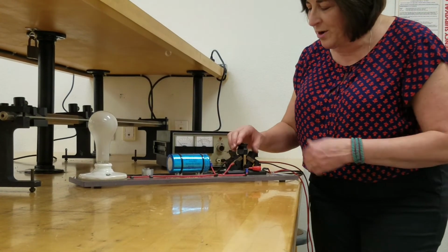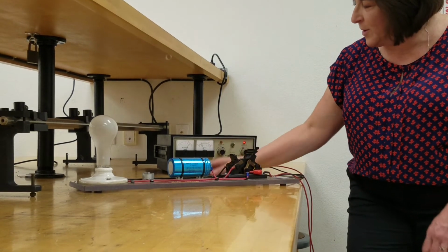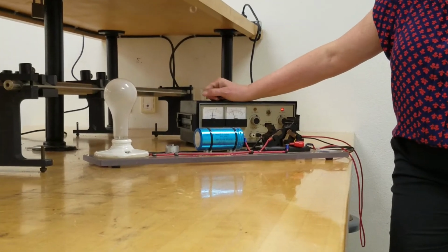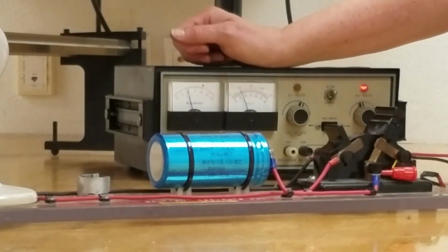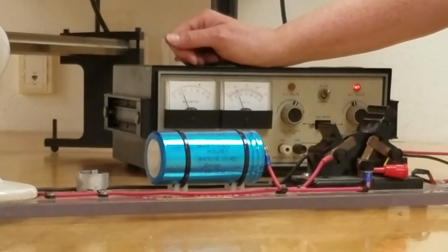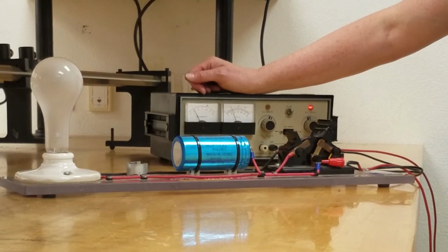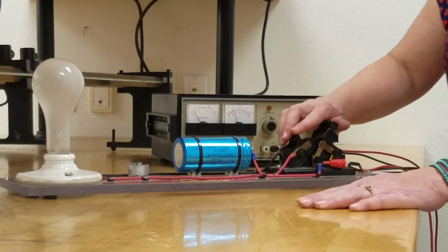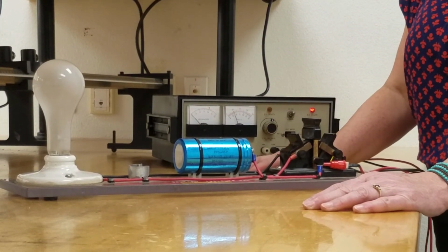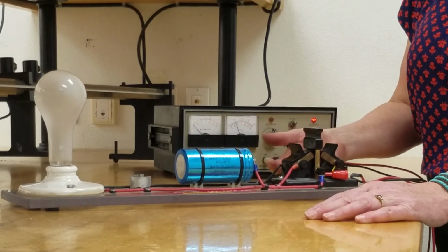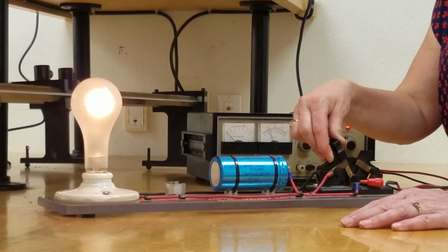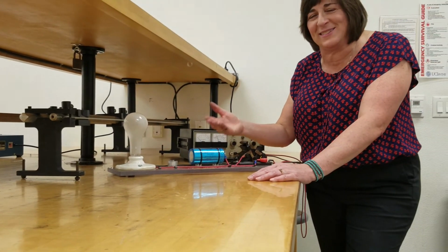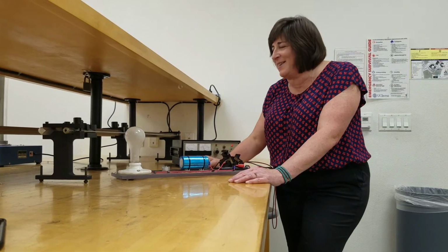Okay, so we're fully discharged now. So we're going to charge it back up. Again, you can see the current was high at first. It'll slowly go down as more and more charge is building up on that capacitor. I'm going to wait till it gets about 95% lower. Okay, that's pretty much fully charged. So get ready to count, see how long this one stays lit. Ready? 1. Not even 2 seconds. So big difference. So let's explain why that happens.